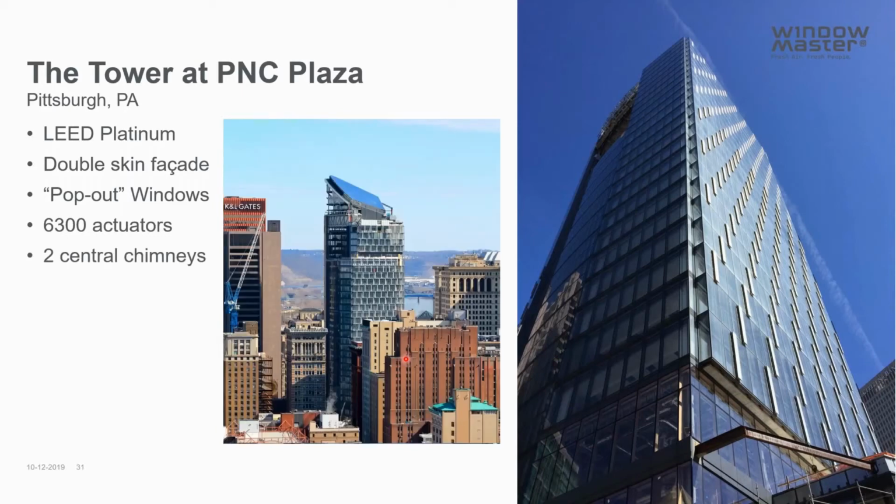In this building, it would also be too wide to have a cross ventilation principle. So to utilize the stack effect to pull the air through the facades and make sure that all occupants are provided with fresh air, they utilize two central chimneys in this building.